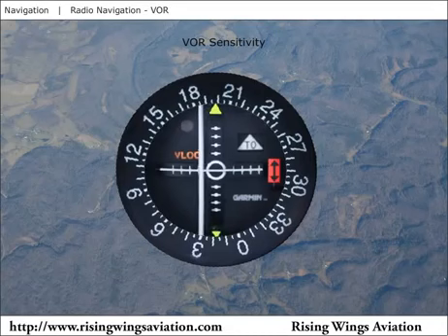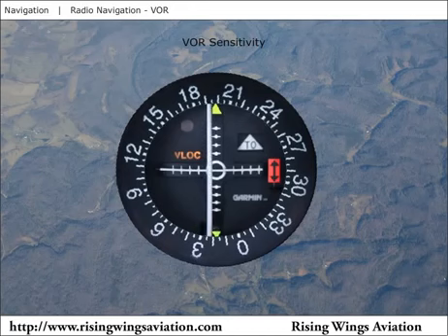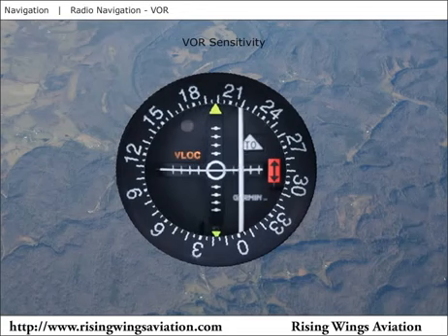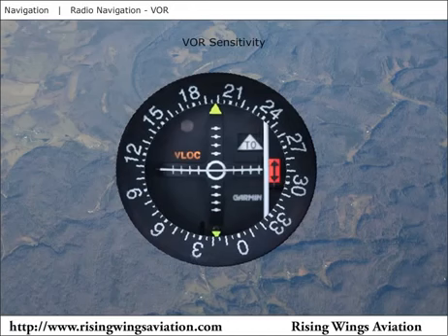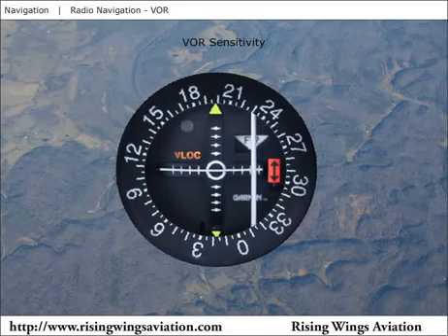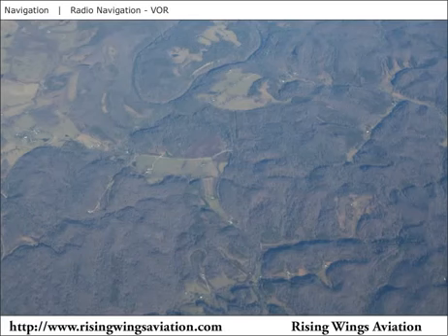When overflying a VOR, the needle will become more and more sensitive until, when very close to the nav aid, the needle will likely swing all the way to the left or right. At these close distances, simply remain on your heading. The to/from flag will change to an off indication as you pass the station. Once on the other side, the from flag will appear. As you track outbound from the station, the needle will become less and less sensitive with your increasing distance from the VOR.